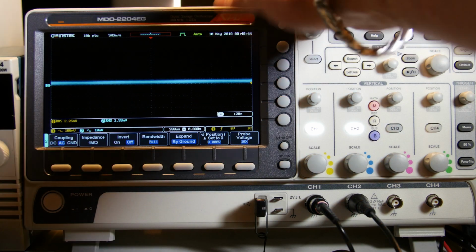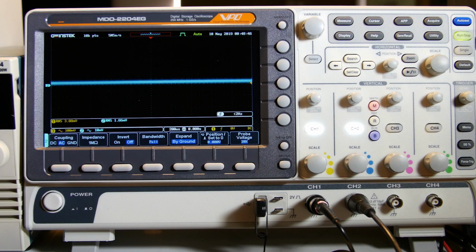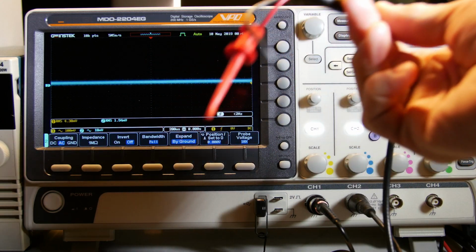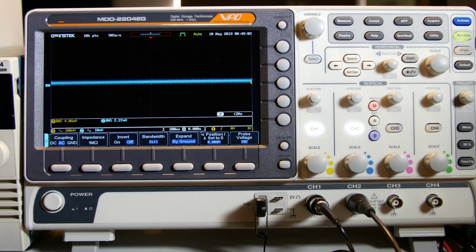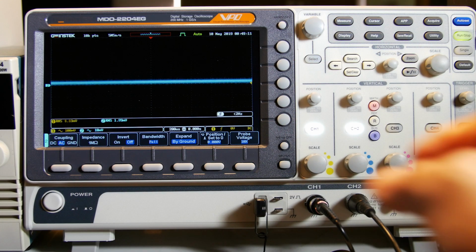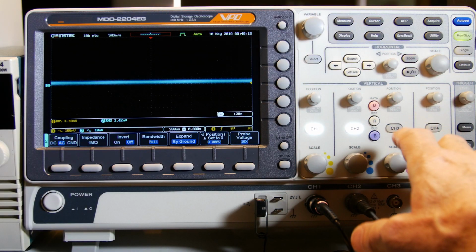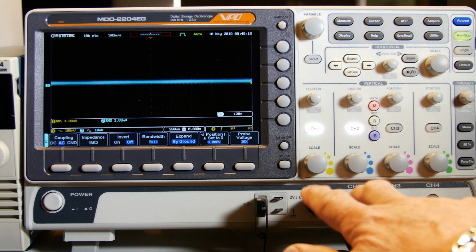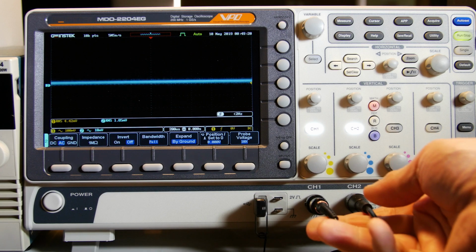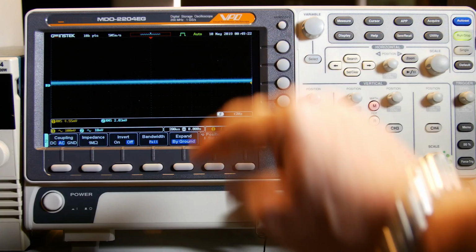Alright, so for the cool part about this scope, we can do this measurement kind of automatically. It has 2 generators in back here. One of them we're going to use for the setup. So we come out of the generator with these little clip-ons that clip onto the devices we're going to test. Then the scope's going to sweep that generator, take readings off these 2 channels, do some division, and give us a gain and phase plot.